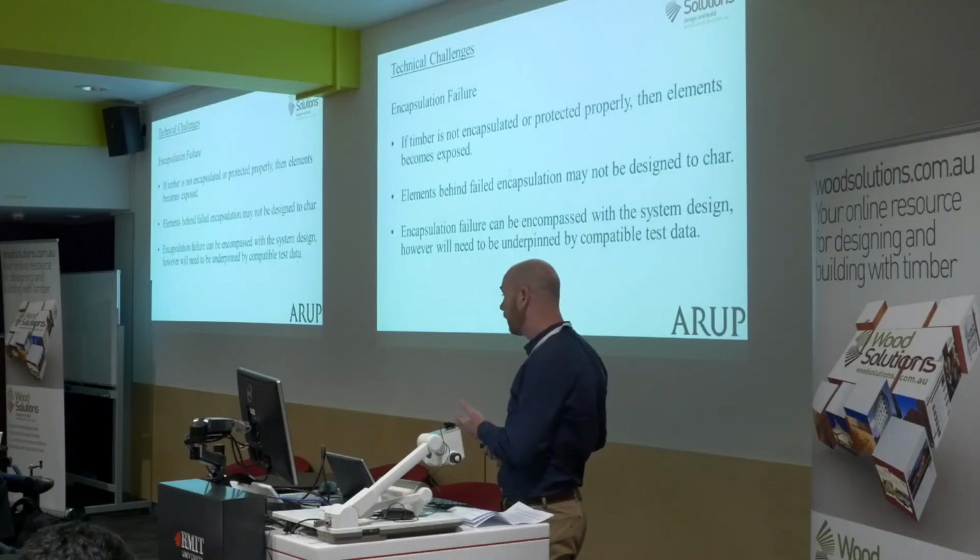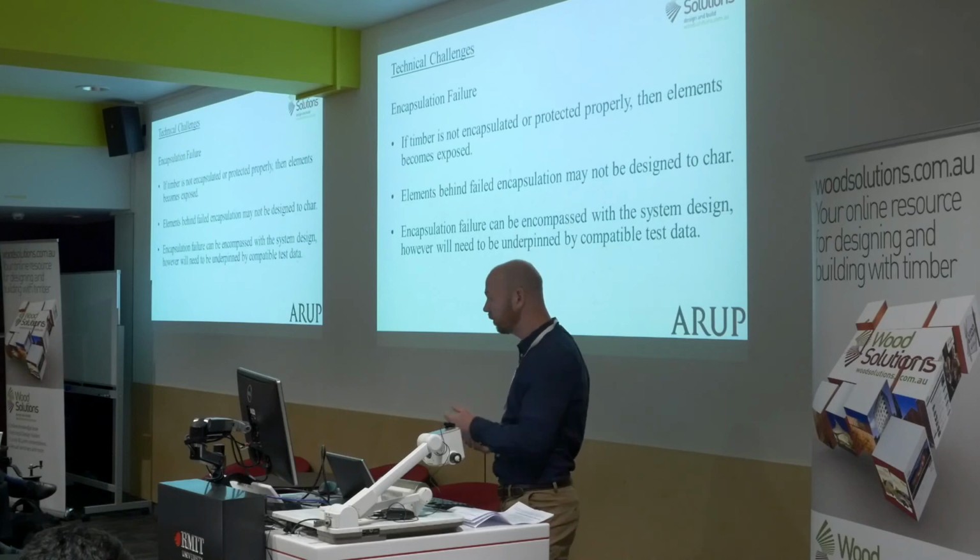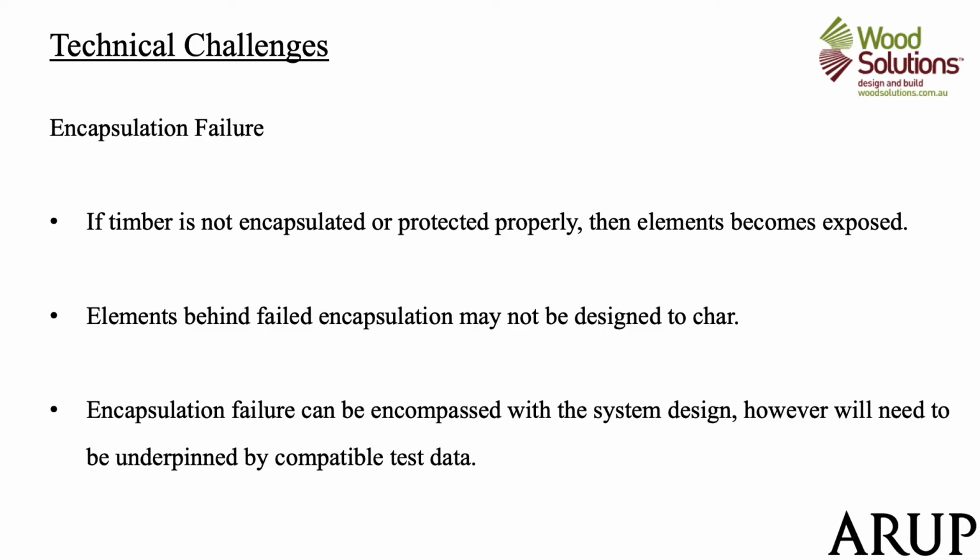Encapsulation, so there's lots of good information from WoodSolutions and others about encapsulation. However, if it's not detailed properly and the encapsulation fails, which many fire tests show that incorrectly detailed encapsulation does fail, either by falling off or using the wrong materials, so that char goes through, the heat travels through the material. If the timber behind that has not been designed to char, then as soon as that's happening, you're losing structural resistance, which can be a dangerous situation.